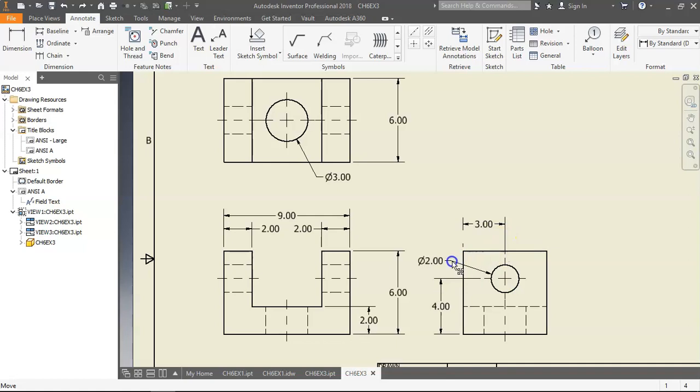Let me see if I can find the cleanest place for it. Oh, that looks decent. You don't want to get too close. Like if I did something like that, that's too close to getting confusing. You kind of want it as close to 45 as you can do. Like that's okay. If you could avoid crossing dimensions, it's probably better, even though that's not technically a rule. This is okay, but now you're getting a little bit further from the part. Pick which one looks good and is violating the least amount of rules. I think I like that over there.